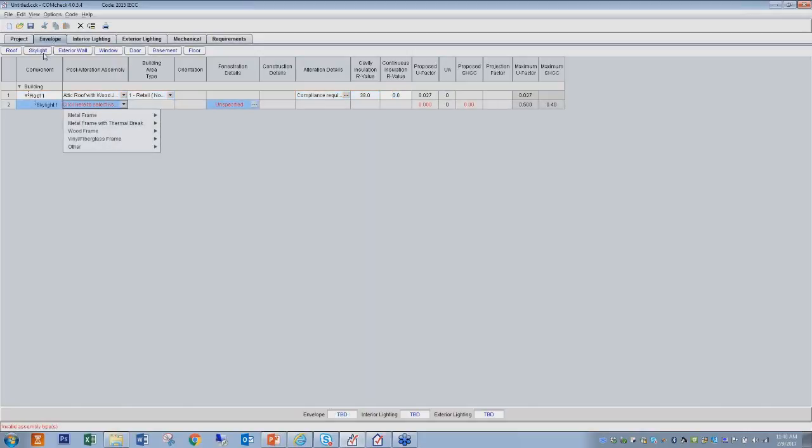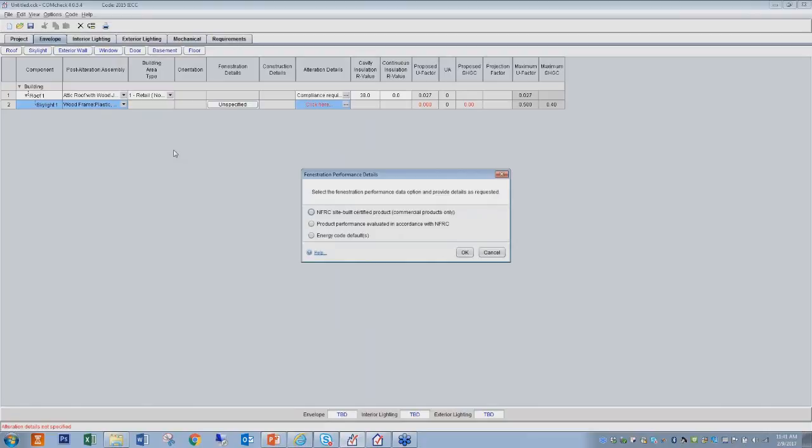All right, let's go to the next one. I'm going to show you skylights, and I'm doing my post alteration. So the skylights that I'm putting in. And remember when I talked about the 3% threshold and the 5%? Let me refresh your memory: you have a skylight to roof ratio that has a limit, or you've got to go total building performance.